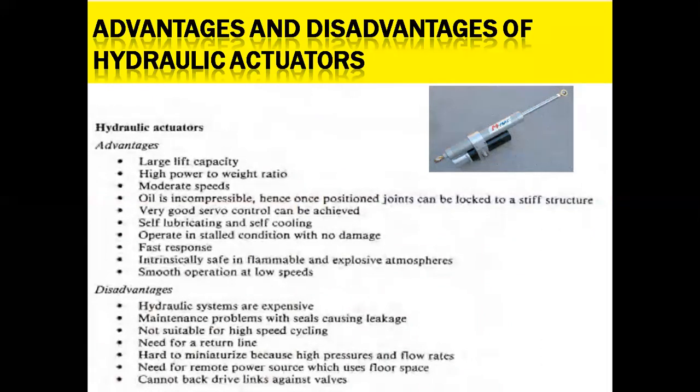Oil is incompressible, hence if needed, joints can be locked to a stiff structure, and good servo control is achieved. Hydraulics also act as self lubricant, whereas in pneumatics we utilize filtration, lubrication, and regulation.